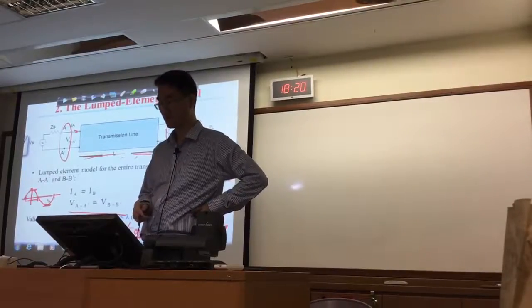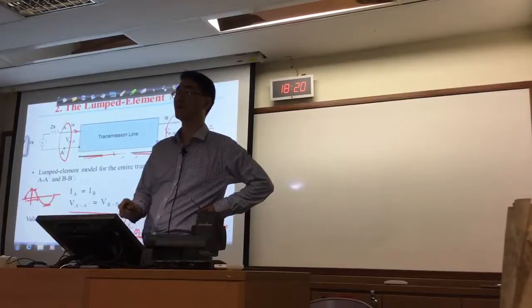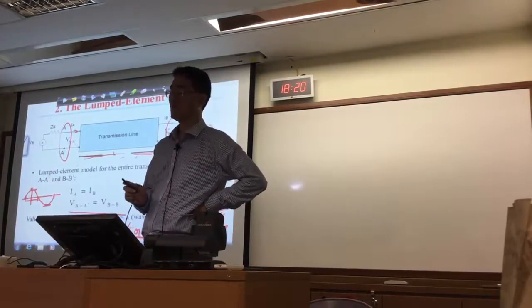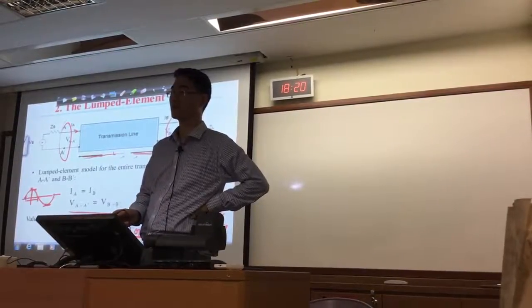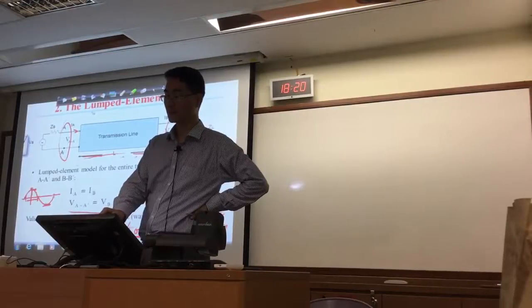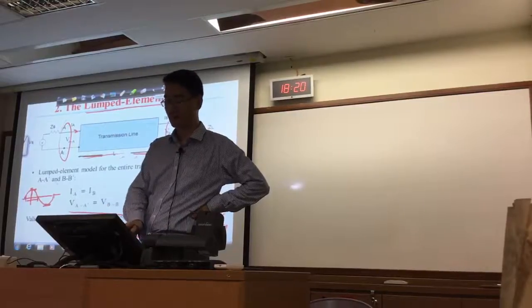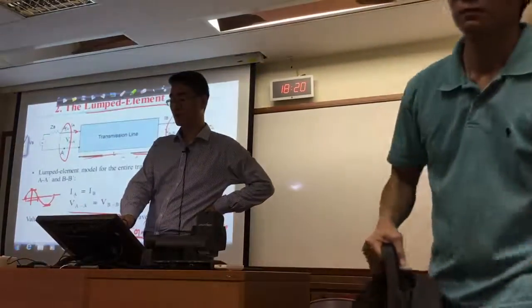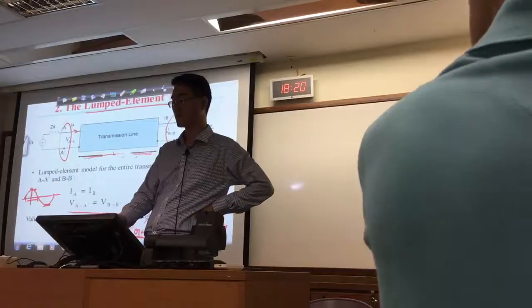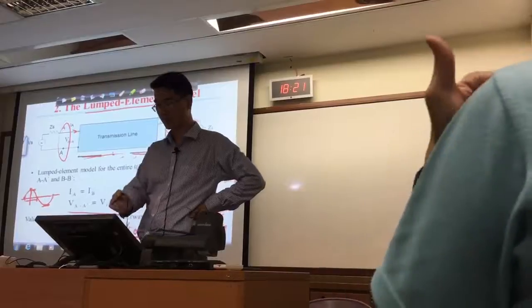This is a big difference between RF engineering and what you have in your mind, which is low frequency electronics. So in low frequency electronics, the so-called lumped element model uses KVL and KCL. So assume the voltage and the current are the same along the transmission line.